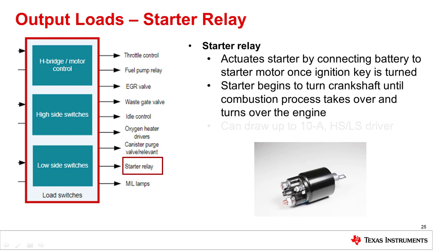and turns over the engine. The starter relay is the engine load that draws the most current from the battery, up to 10 amps depending on battery voltage and size. This can be powered with one high side or low side driver.